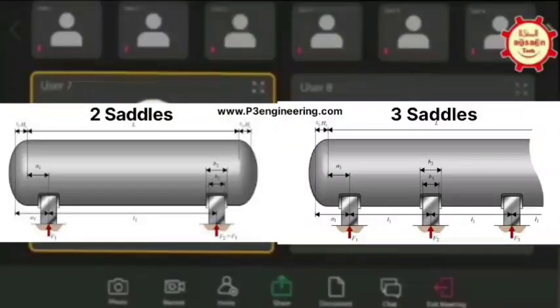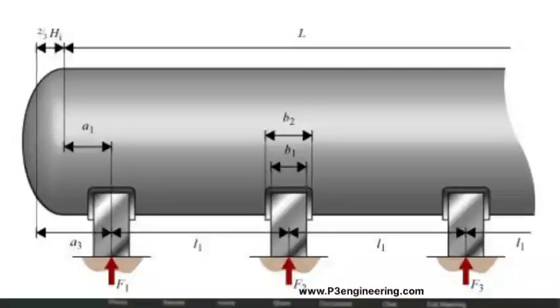Himanshu, I suggest maybe your structural guys can help in that case. Yes, maybe, or maybe FEA will. Yeah, FEA is fantastic. I mean, you need not ask anybody. Yes, better. Because with FEA, again, they have to model the complete vessel. Then they have to add the saddles and verify which portion particularly is failing. They need to analyze all three saddles, and then verify where it is actually failing.